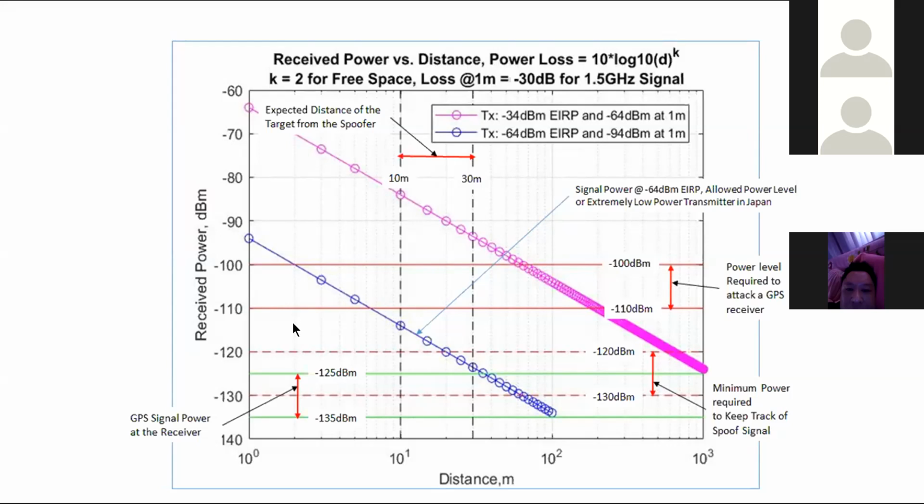If this signal is a little bit weaker, say around minus 115, it will interfere. The receiver may still work, but it will not work with good accuracy. Okay? But if it is above this, some signal or noise, it will totally jam your receiver. And if something is around minus 100, then this will totally disrupt your receiver. Nothing works here. Okay? The power is too much, too strong for the receiver to work.